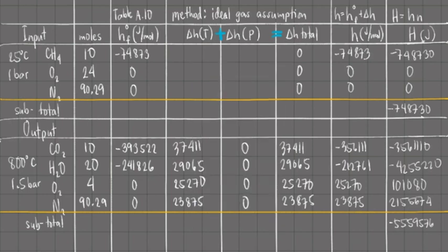At this point, we have finished our determination of the enthalpy because we were able to get the summation of the enthalpies of the reactants and the summation of the enthalpies of the products. If you go back to our simplification of the energy balance, that is, the rate of heat transfer is equal to the summation of the enthalpy of the products minus the summation of the enthalpy of the reactants, we can actually now solve this to determine the rate of heat transfer from the reactor.